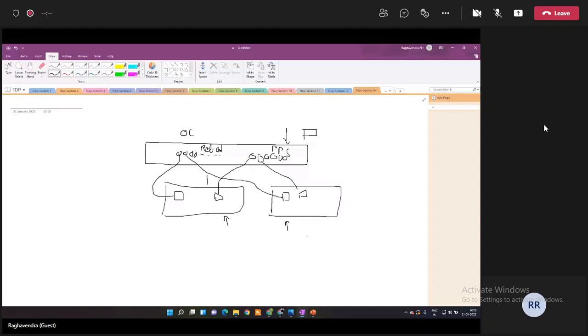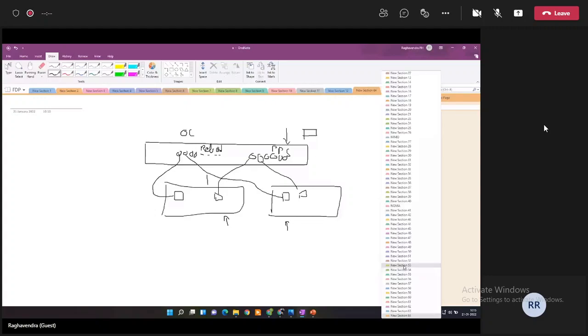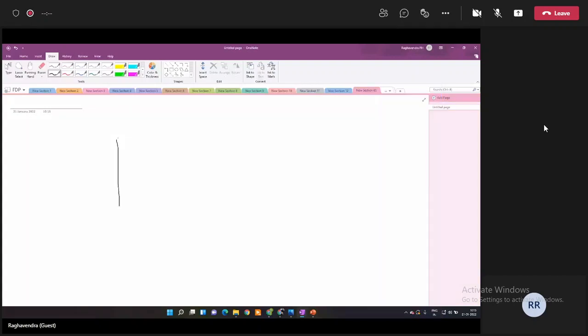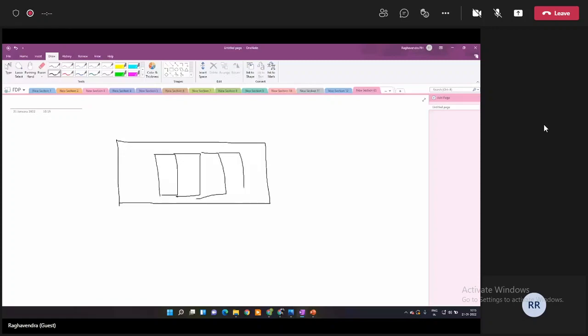Okay, if not, I'll move on to what I was talking about yesterday, right? So yesterday I was talking about the PXI chassis system. Just to recap, a chassis system is something that will allow us to have multiple slots in it, which allows us to take data from multiple data acquisition cards that are there. There are ports inside which properly fit with the data acquisition cards that are there.